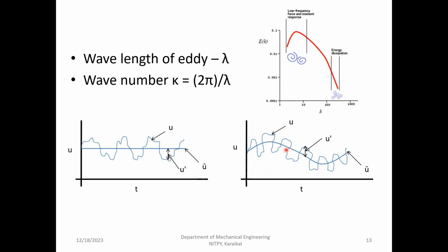If I want to do that for an aircraft, or any test section that is 1 meter long, and the test experiment takes something like 20 minutes, the time taken to complete the simulation is going to be really difficult. We will not be able to do that. So that comes the problem. So then people started to look into it. They said that velocity is going to be an average velocity plus a fluctuating velocity. Okay, so now what can we do with this?